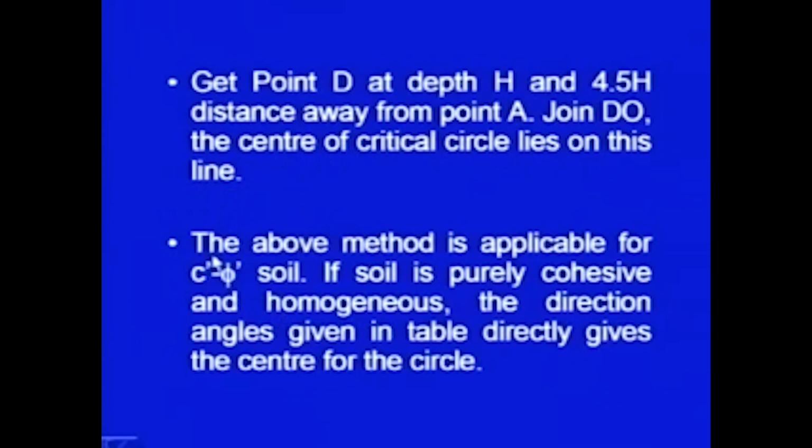There is a note here: this method is applicable for C dash phi dash soil. If the soil is purely cohesive and homogeneous, then the direction angles given in this table directly give the center of the circle.